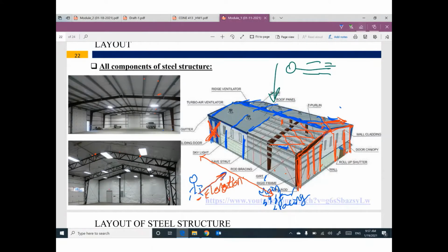So guys, for dead load, we have weight for the main system, in this case our frame, or in this case, our truss. We have something called purlins. Do you remember that? These purlins are in the longitudinal direction like this for a frame, or like this at each joint for trusses.